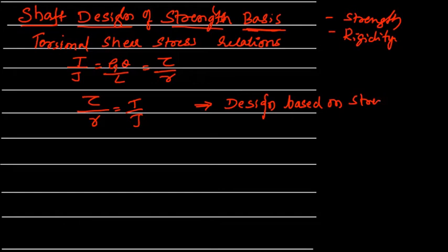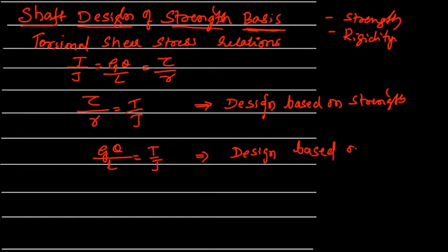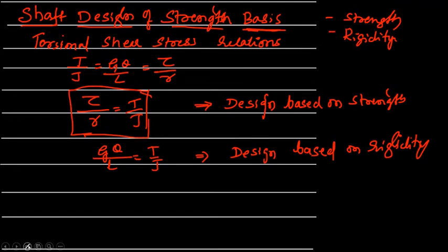Now the relation G theta by L equal to T by J stands for design based on rigidity. Design based on rigidity. Clear?